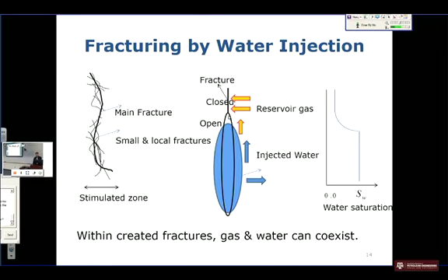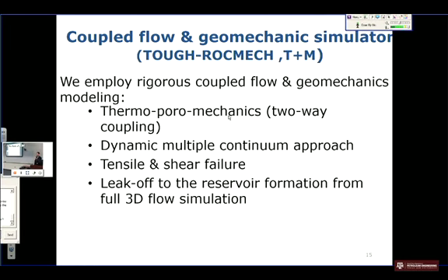Which one? Shear failure? You don't have to go back, it's just a quick question. The corresponding strain condition that will generate the crack, is it non-associative? I mean the flow rule, you mean? Yes. We could use an associative flow rule or a non-associative flow rule.